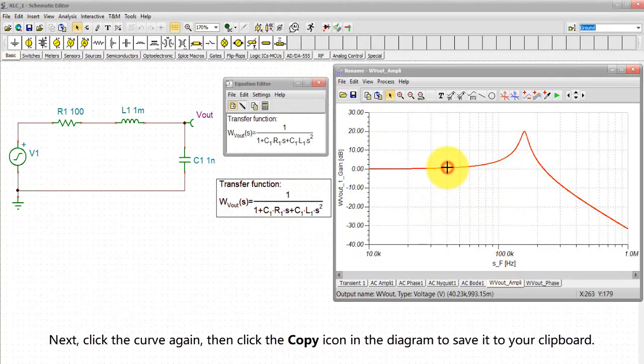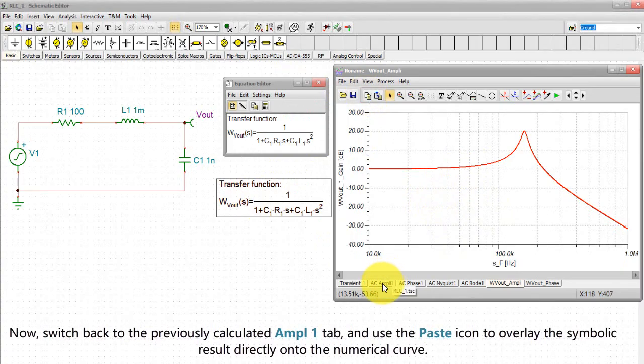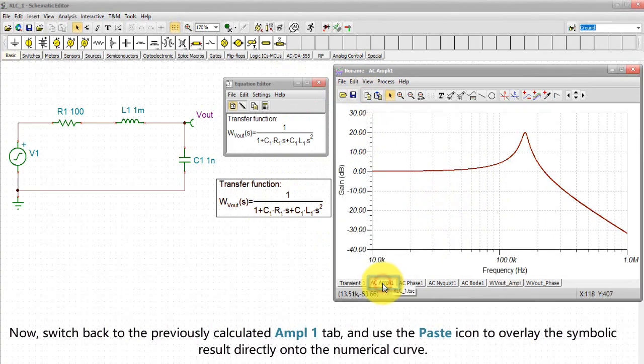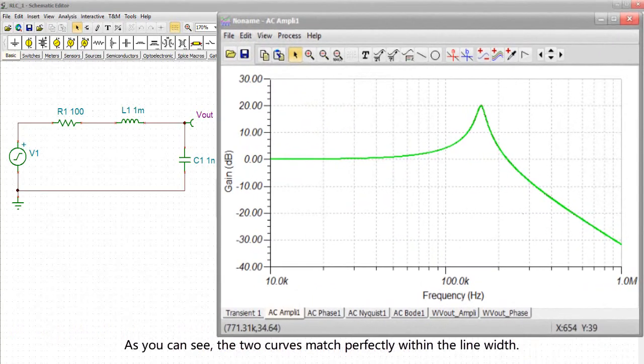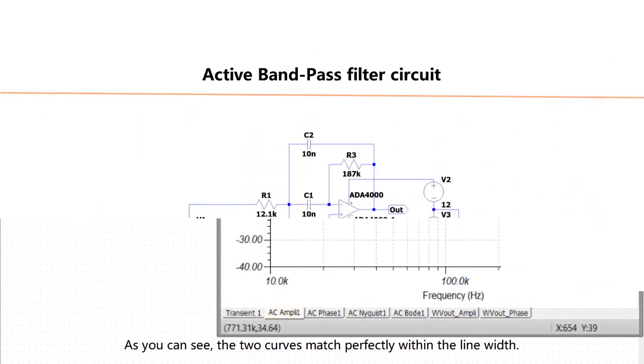Next, click the curve again, then click the copy icon in the diagram to save it to your clipboard. Now, switch back to the previously calculated Ample1 tab and use the Paste Curve icon to overlay the symbolic result directly onto the numerical curve. As you can see, the two curves match perfectly within the line width.